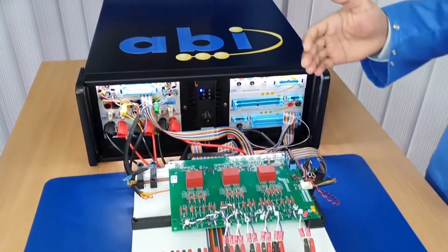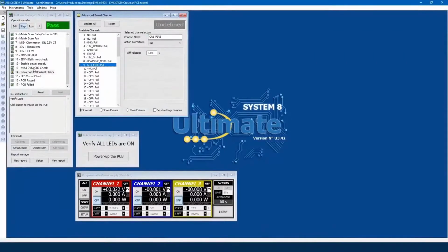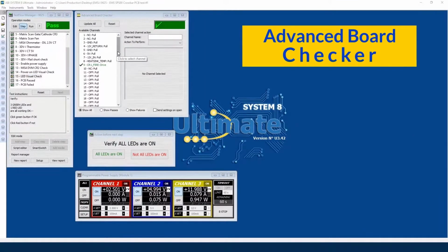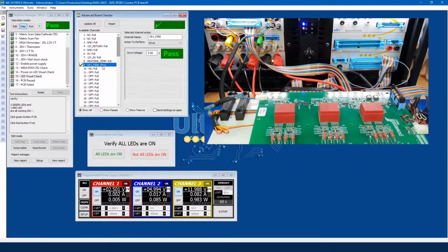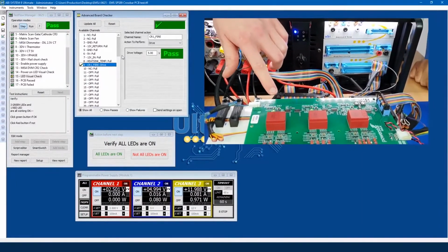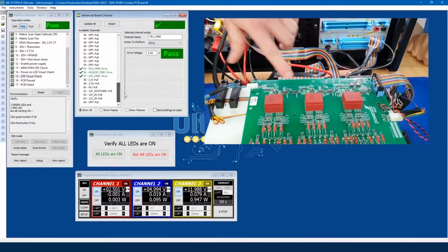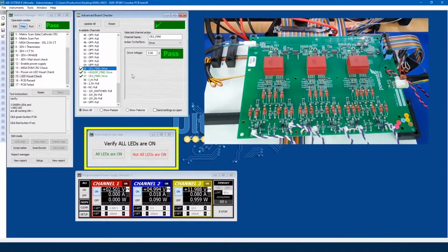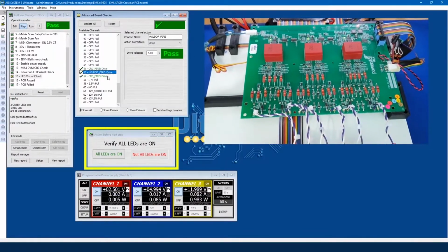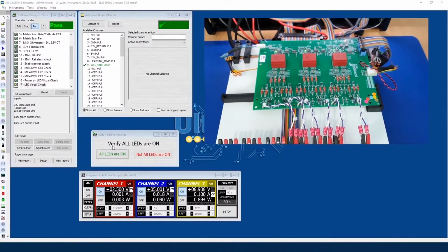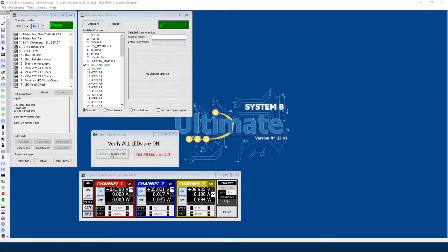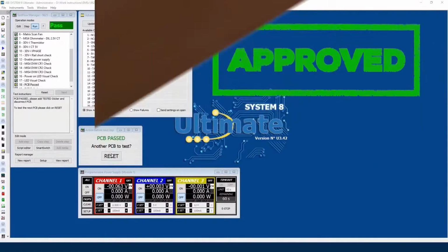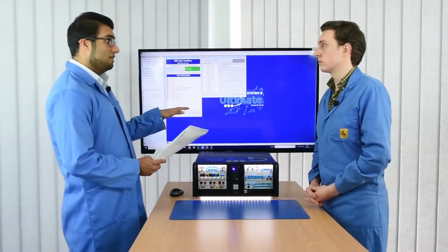Couldn't be easier. And we had a look at the Advanced Board Checker, which has 64 channels, and for each one of those channels you can choose from 4 states. You can have pull, so when you turn it off, it's at a set voltage. Most people probably choose 0, but there's an option to choose a higher voltage. We also have drive, which drives that pin at a voltage you choose. Sense senses what that voltage is, kind of like a 64 channel multimeter, and the final state you can choose is a VI test. Wow, so you could do a complete board level test with this.